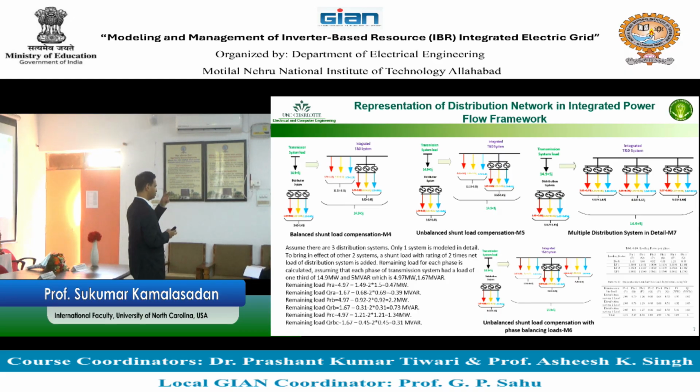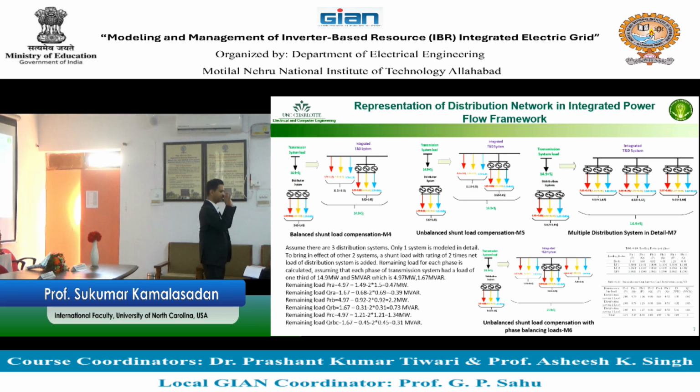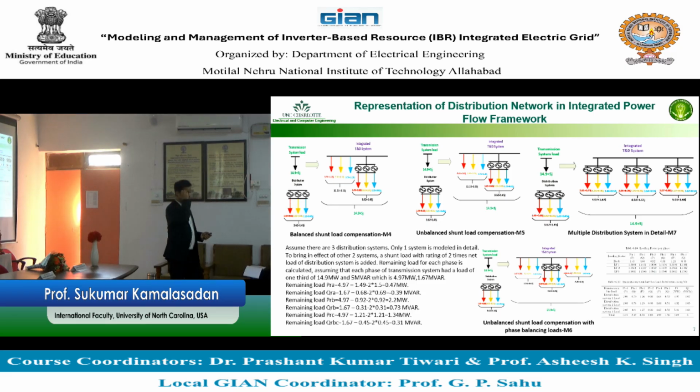Okay. So there are two very critical steps to solve the problem. You understand the problem? Transmission system and distribution system running together. One challenge is that the transmission system is mostly modeled using what we call positive sequence representation. The distribution system is running in three-phase representation. So you have to stand where? Sequence or phase. If you want to run them together, we will find a way to solve them together.